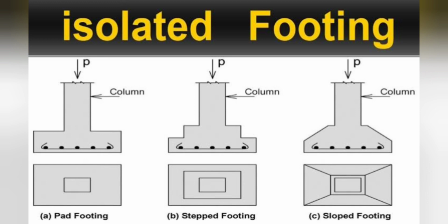Next we have deep foundations. These types of foundations are used when there is poor condition of soil near the surface, which means the bearing capacity of soil is very less. Pile foundations are a type of deep foundations with long vertical load transferring members made of steel or concrete. Piles are in fact small diameter columns which are driven or cast into the ground by suitable means.